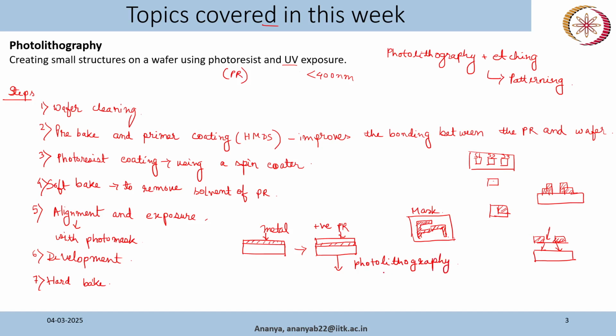So by this I mean that you will align your mask and you will do exposure and development. So the structure you will get will be like this. So this is your substrate and this is your metal.